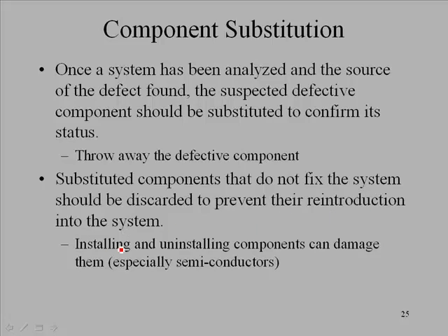Installing and uninstalling components can damage them, even in the event that you have components that are good, you install them, then you take them out of the system. Those components should not be reused. Semiconductors are relatively inexpensive, and they can be damaged by putting them into a circuit and taking them out of the circuit, so it's better just to dispose of those and not put them in with your known good components.